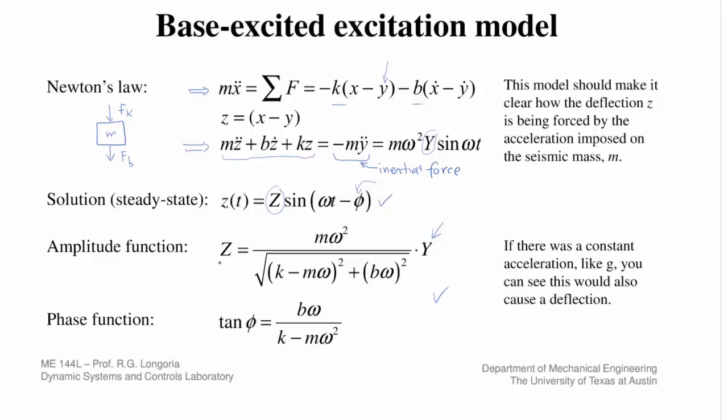All right, so this shows you how the spring would deflect, the peak deflection would be related to the amplitude of the input for a sinusoidal input. And all you'd need to know then are the mass, stiffness, and damping, as well as the forcing frequency. And you could find out what amplitude you have in the oscillation of the mass. But again, if you're doing vibration analysis, that's something you would do to find out how much that mass is moving.